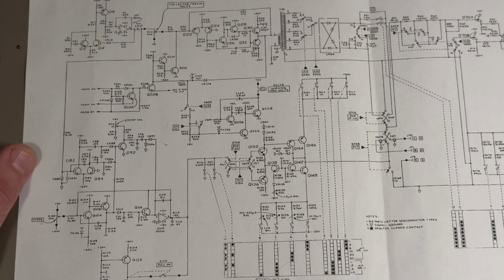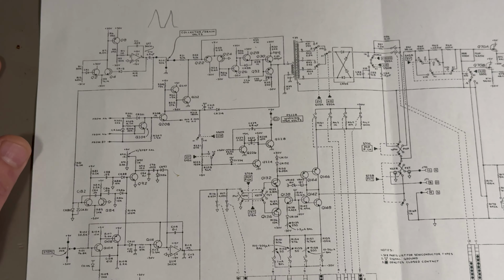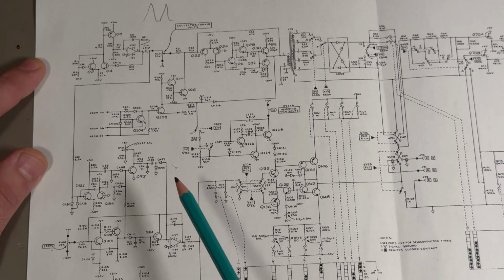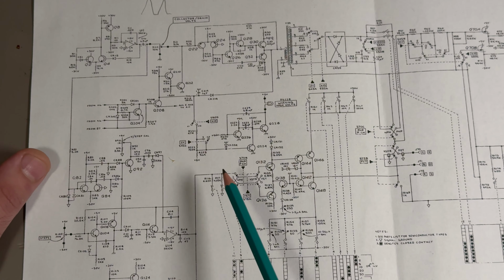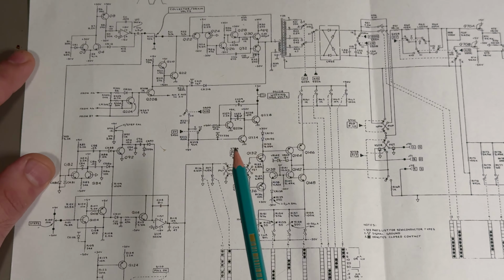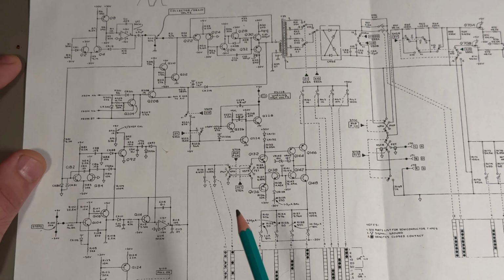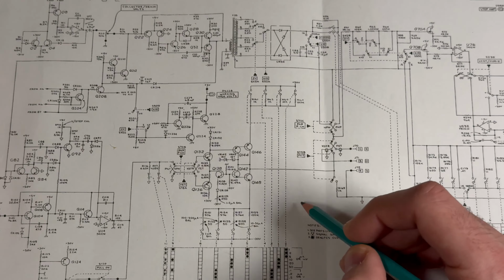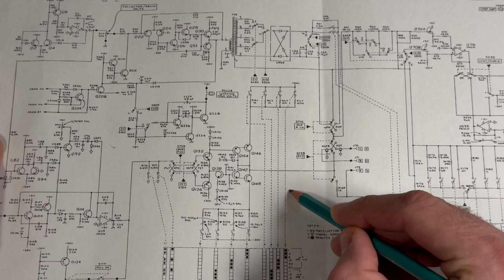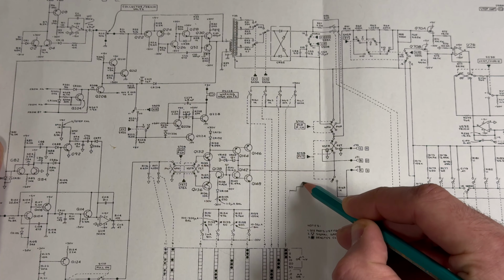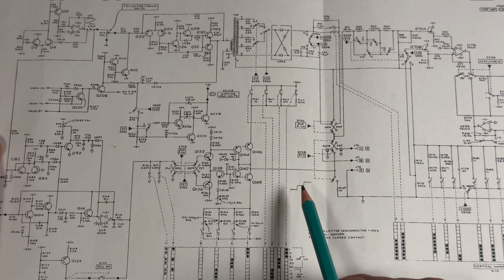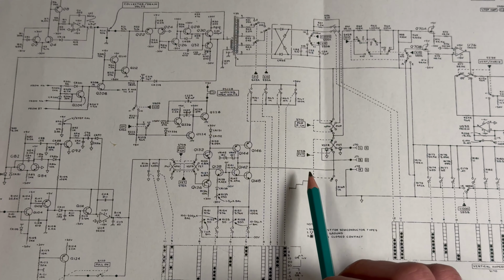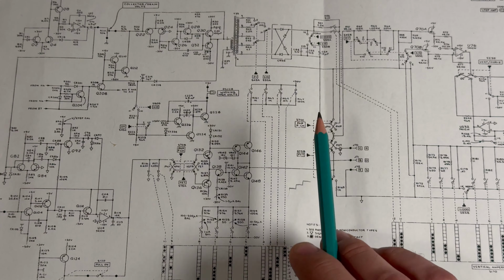Now, some of the interesting aspects of this device here are there's no logic responsible for generating the step pulses. So for every sweep of the collector, there will be on this point here basically a voltage or a current step that kind of looks like this. And how would you go about doing that without a counter or some DACs or some stuff like that? Because remember, this is a 1970s device.